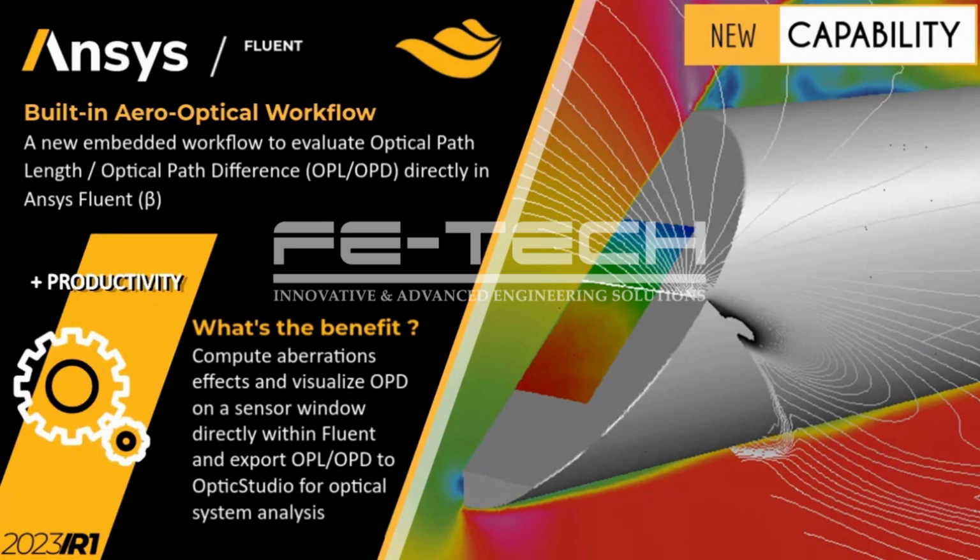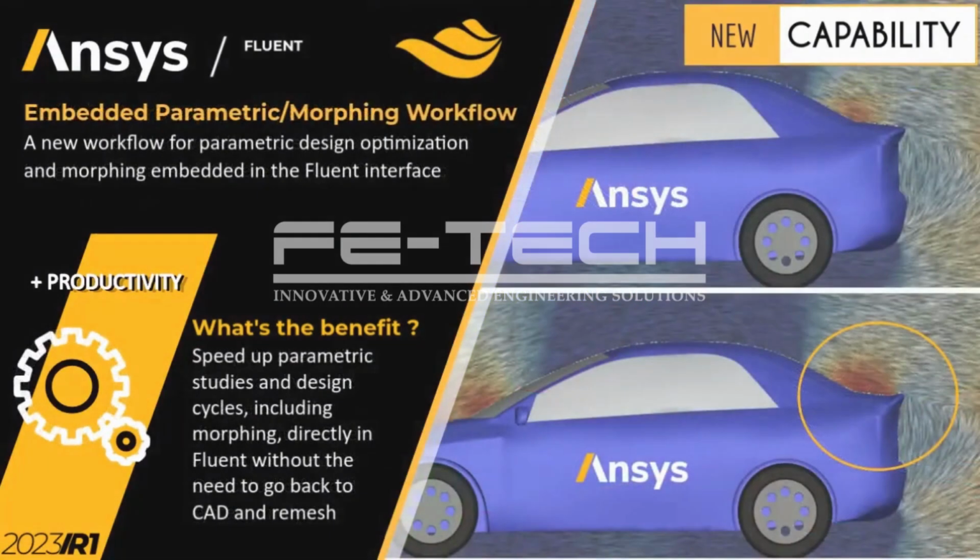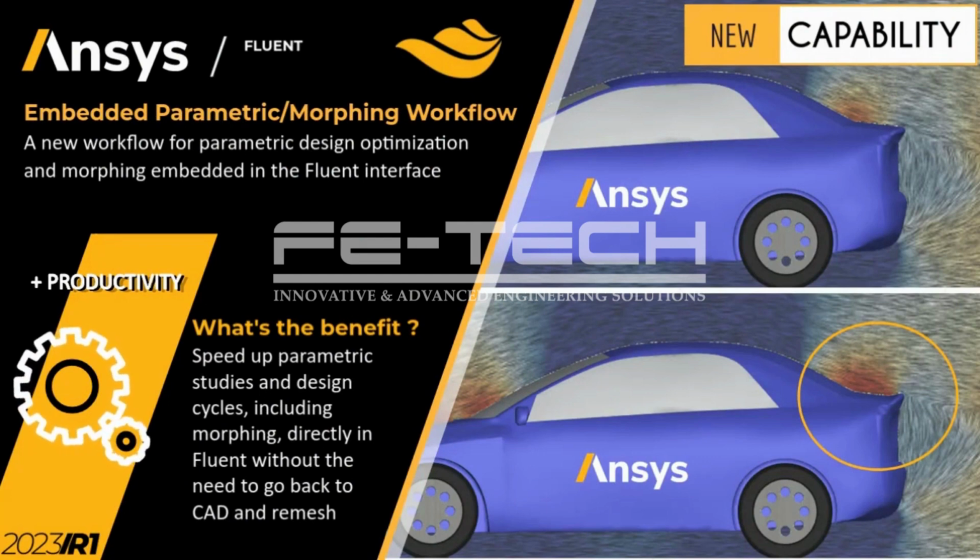You can now compute the optical path length and optical path difference due to aero-optical aberrations directly in ANSYS Fluent and export them to OpticStudio for more sophisticated optical analysis. A new embedded workflow for parametric design optimization and morphing enables you to run parametric studies and design optimization, including morphing, directly within the Fluent interface, thus speeding up design cycles.